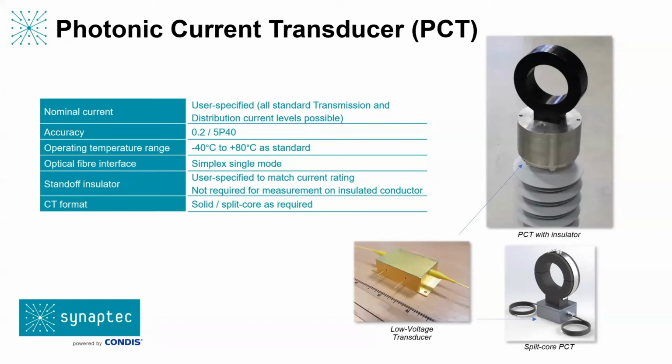So one other thing for you, Stephen, if I may. There was another question about the protection algorithm being deployed by us. We should probably explain the distinction between how the interrogator would publish sample values onto a process bus in most digital substations, but your example went a bit further than normal by actually running the protection algorithm on board. Could you distinguish the different levels of software functionality within the interrogator unit? I think that provoked at least one question where people were confused about how we interact with protection relays and traditional schemes.